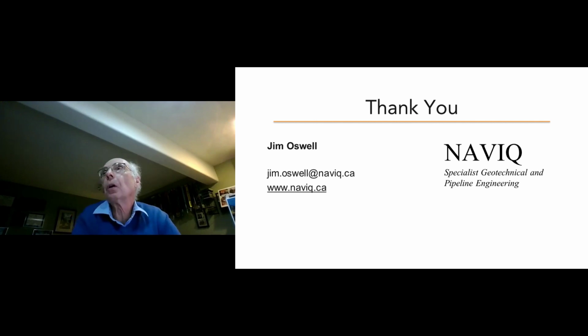Okay, so yeah, that's really important because an HDD that will go down, say 30 meters or 10 meters, the temperature of the ground down in that HDD bore is going to be much, much warmer than the air temperature is going to be, particularly in winter. Generally at below about 10 or 15 meters depth or 20 meters depth, the ground starts to warm up all the way to the center of the earth.